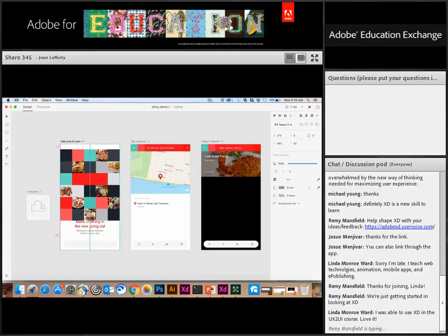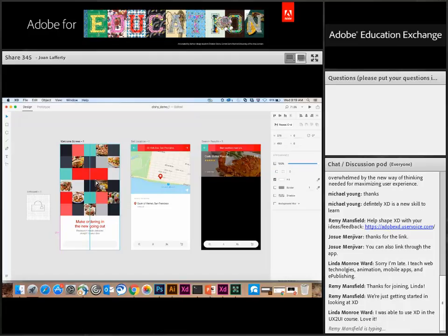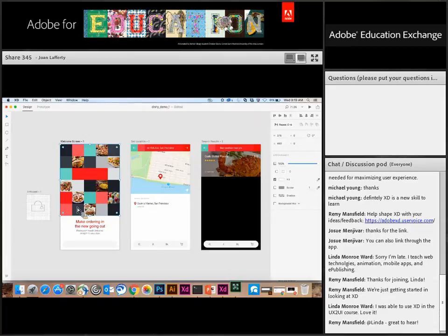And then as you can see, as I move around, we have various measurements that show up as smart measurements. If you want additional measurements, you can click on the Alt or Option key on your Mac. So I'm going to click on that, and now whenever I hover over any item, you'll be able to see the measurements. So here I am clicking on Alt, and you can see the measurements between various objects that you have selected and that you're hovering over. And so again, you just click on the Alt key to be able to see those other measurements.